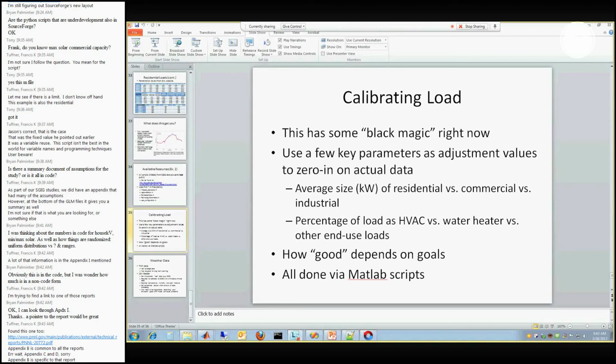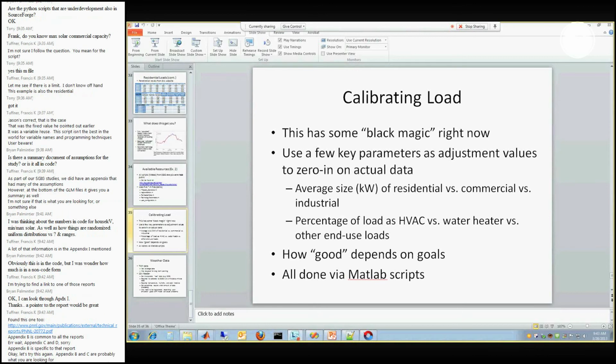We'll try to match those 4 days really, really well. We'll spend some time modifying the load shapes a little bit, modifying the house VA value, penetration levels, things like that, until we're happy with those days, and that becomes our settings.